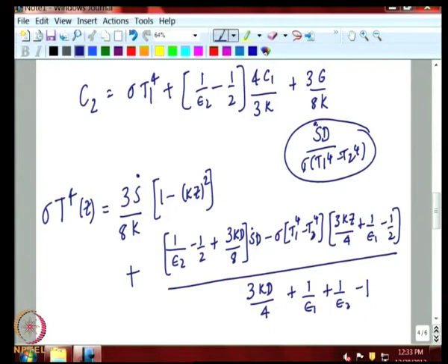But on the other hand, if the heat generation is small compared to the flux difference between the two walls, then this term drops out, and then you are left only with dealing with this expression here. So, in this more complicated problem, where heat is added volumetrically to the gas as well as heat is coming from the two walls, the relative importance of the internal heat generation and surface heat transfer is driven by this non-dimensional parameter.